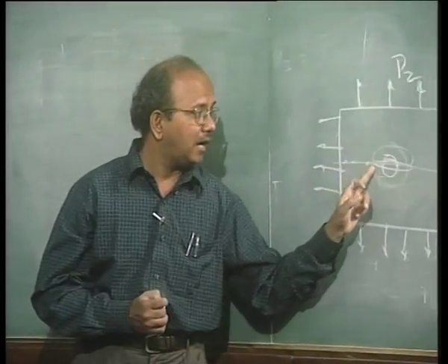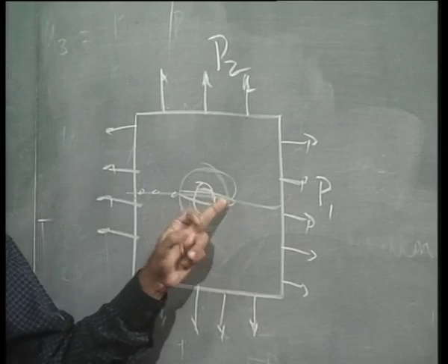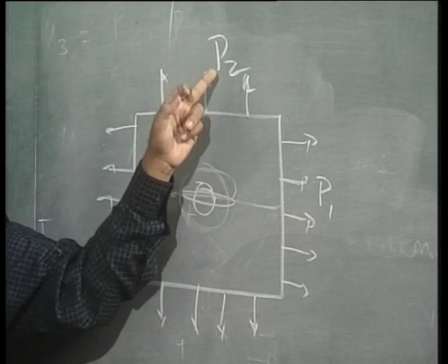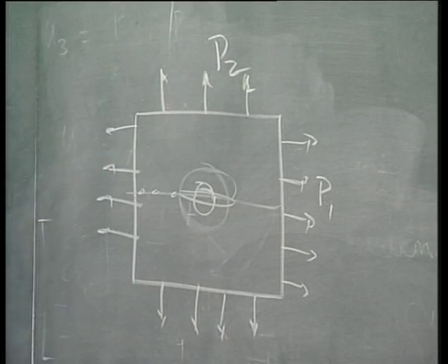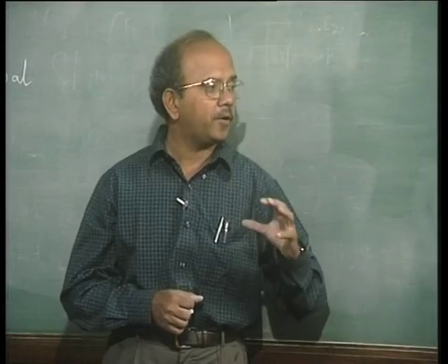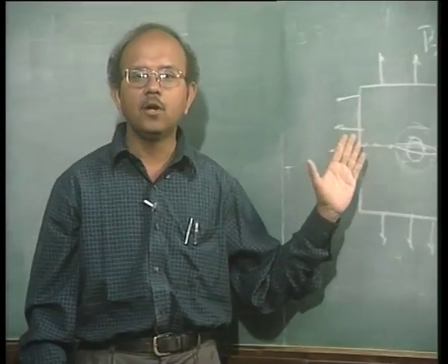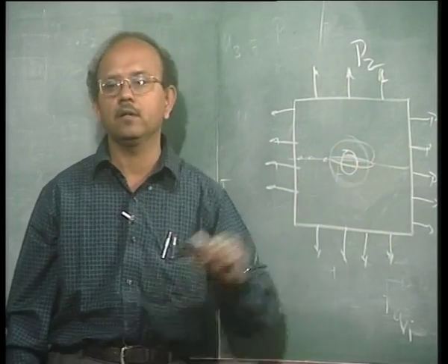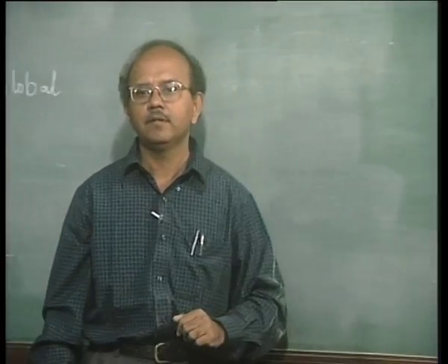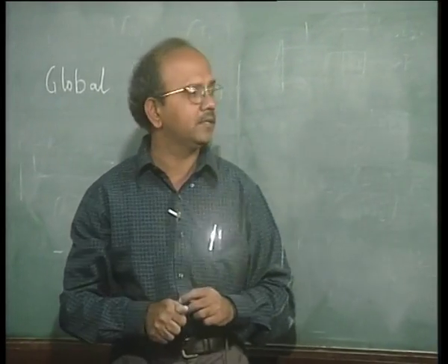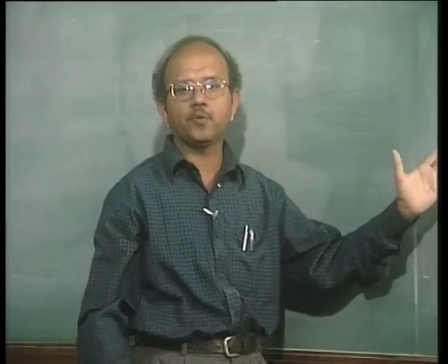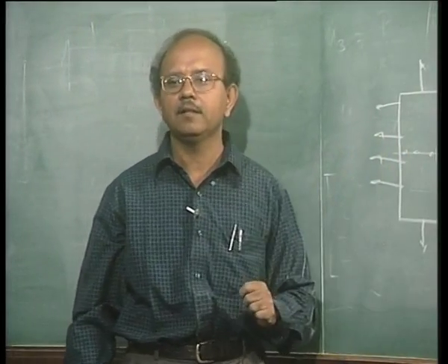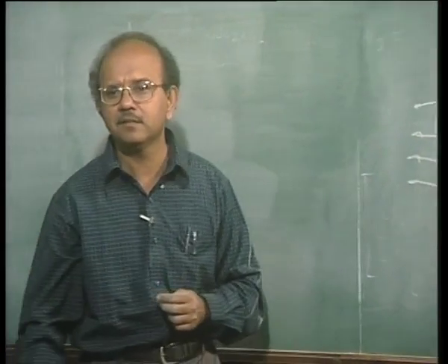In fact, when the hole is very sharp, stresses may even reach infinity. Okay, there's a singular point and so on. Let's not worry about those things now, but it's important to realize that now the stresses would change as I move away from this corner. If I use one area, as you said, if I use just the projected area, the normal area, then I would get only one answer,